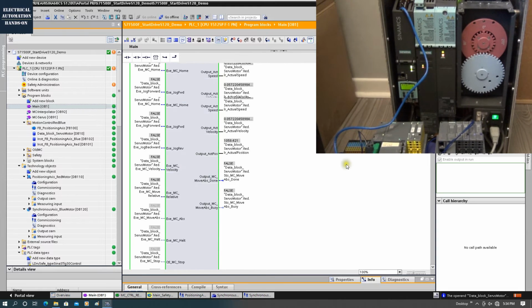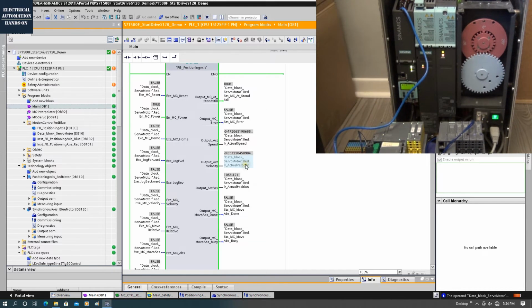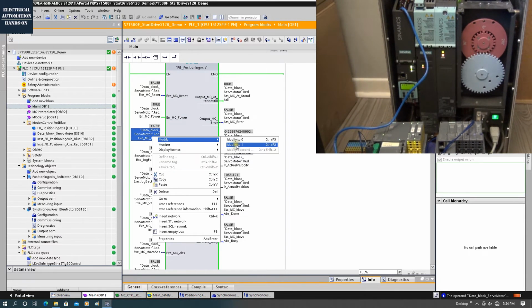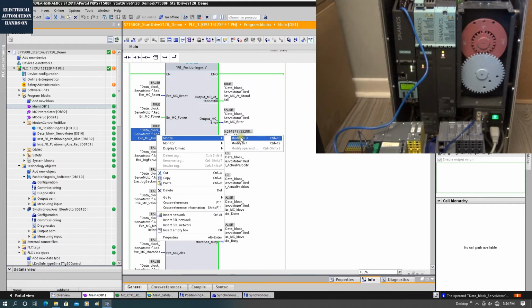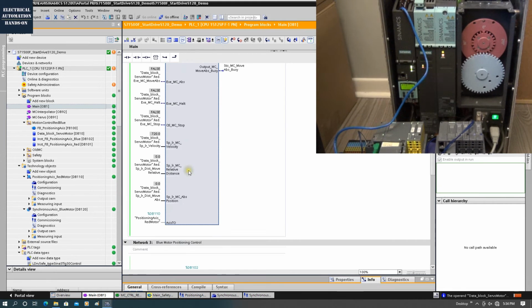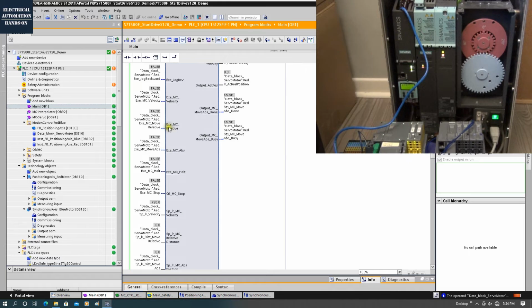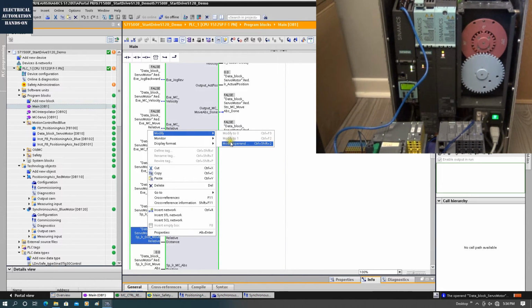Okay, and now I will home the axis again. Let's try the relative move and the absolute move. Home the axis, and in the meantime watch this actual position. Trigger, write 0. And now I will set the relative position move, relative distance. Let's set 1000.